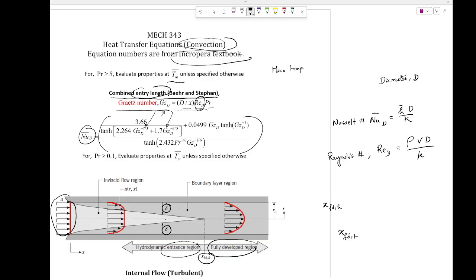Everybody got it? Okay, so this Prandtl number here, where are you getting the Prandtl number value, by the way? From the table in the appendix. You've done it before. Now I remember Mitch was asking what temperature we'll be using, remember that in the exam? I said go to that table, and he found a bunch of temperatures and was wondering which one to use. Then you probably used the film temperature, if I'm not mistaken. Now, what temperature would you be using in this case? The mean temperature. You don't have a film temperature to use here, right, Matt? So the mean temperature you'll be using.